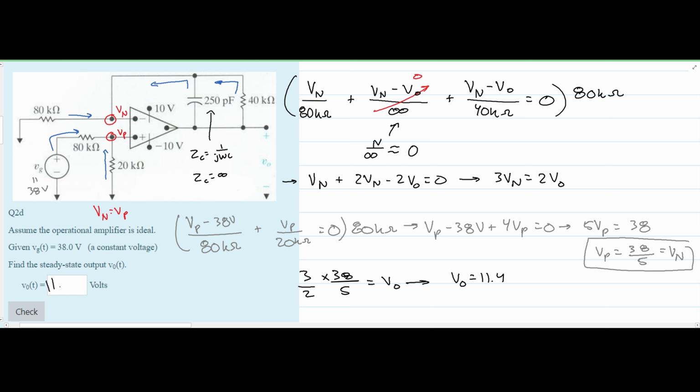So you would write this down here, and then you would be completely wrong. Because if we look at our op amp, we have this max of 10 volts and this min of negative 10 volts. We can't go above 10 volts, and we can't go below negative 10 volts. So if we get a value that is above, like this, this negative feedback is going to go back in here, and we're only going to get this 10 volts.